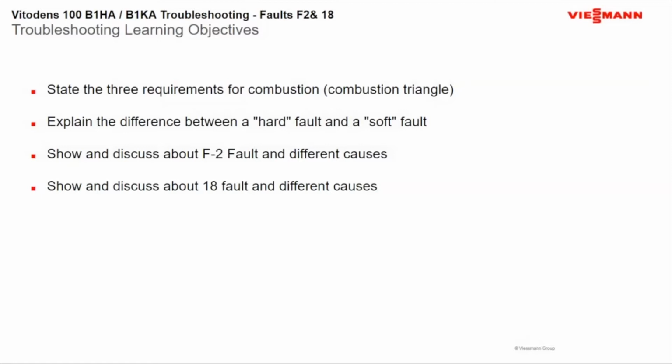So what we're going to go over today is, I always leave this one up, the requirements of combustion, because we always seem to tend to forget about the basics when we go to troubleshoot. So just remember the triangle. Not that this is going to be in any of the presentation today, but I always leave that up because even myself, after doing this for a lot longer than 30 years, sometimes you start to think of the hard things before you even look at the easy things. So the other things that we're going to explain are your hard faults on this boiler as well as your soft lockouts.